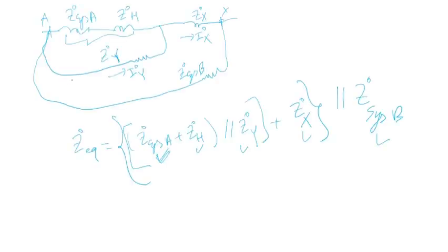So now in this video, we'll go through and calculate the current. If you see the current that flows through the tertiary, or Y side, I'm going to use current division. This current I0Y is equal to I0X times the impedance through the high side, system A plus the high side, divided by the sum of those two plus the zero sequence impedance of the Y.